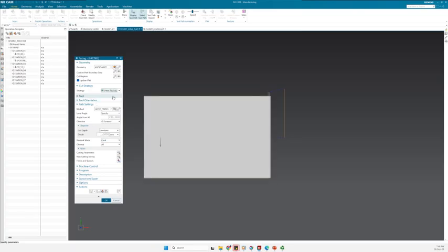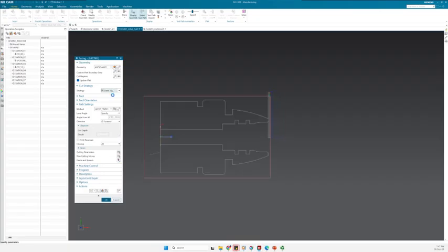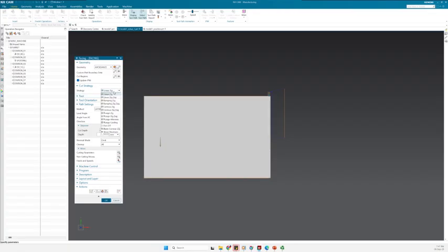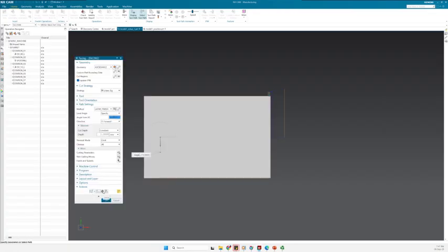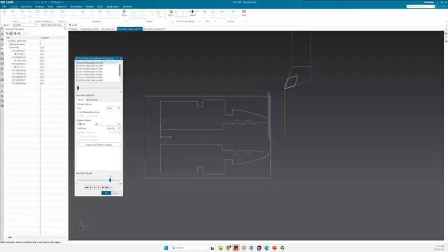Then there are different types of strategies like linear zigzag, contour zigzag. So you can see that there is a little bit of change in the different settings. So I will first, again, generate and verify. I don't necessarily need to do this 2D material removal. I can just click it like that. 1, 2, and 3 passes. It goes to home. Again, I can check that there is no collision. Everything is fine. So now our facing operation is done.